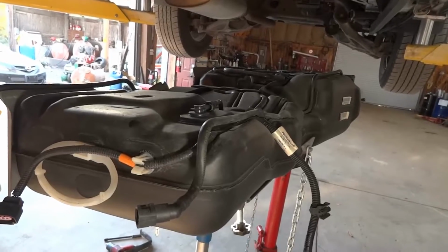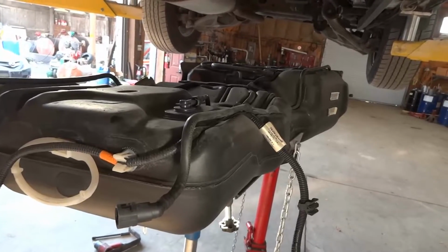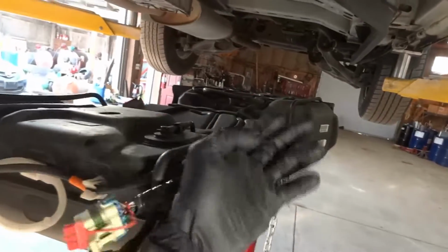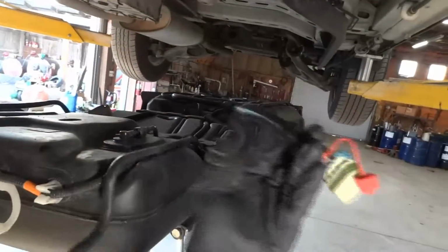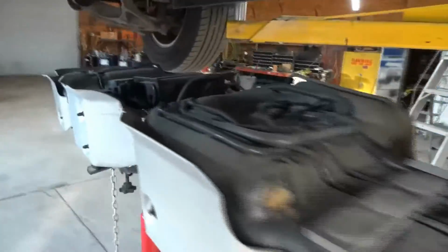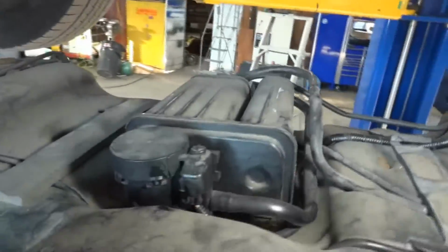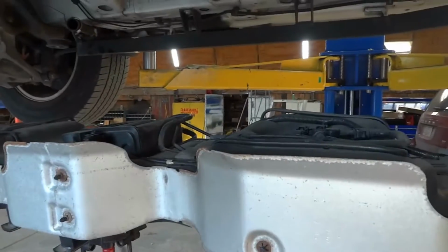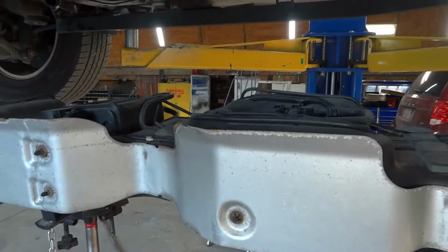So this was an unusual Evap vent solenoid issue. So we got down to it. I fixed the wiring harness. As you can see, it's fixed and ready to go. I got it up on the fuel tank, and I reused the old vent solenoid. So everything is back together. So here's our wiring harness. So now I'm gonna reinstall the fuel tank. After I get the fuel tank installed, I'll bring you guys back up.